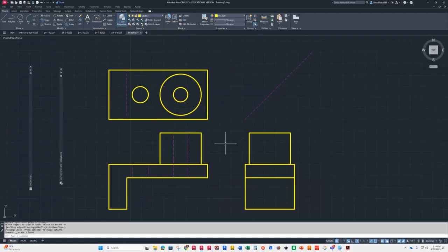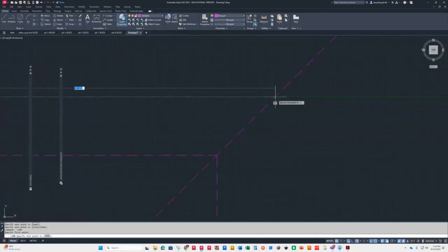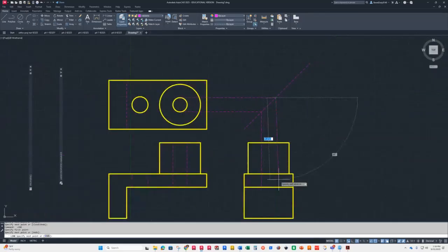All right. And then, just change over to a hidden line. And we can do the same thing. Draw this over to here. And since this one went all the way down on the front view, it goes all the way down on the side view. Make sure when you come over here, you hit the intersection and not the midpoint on that guy. Or at least I got too close.